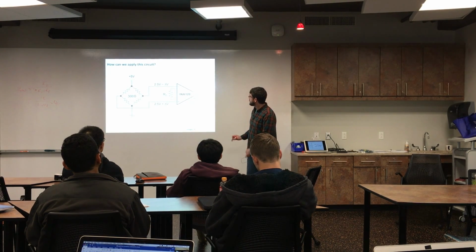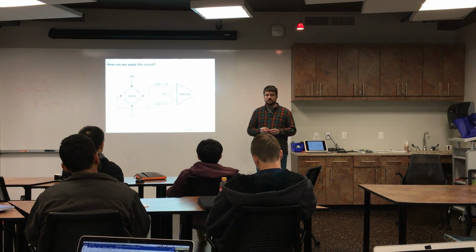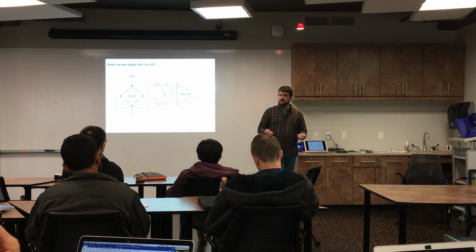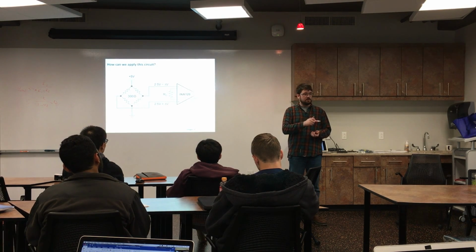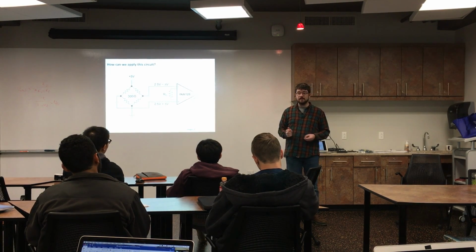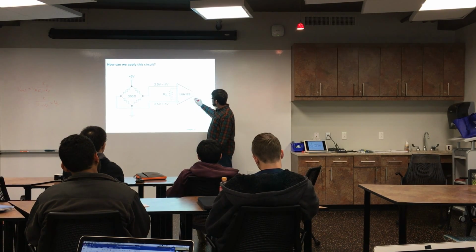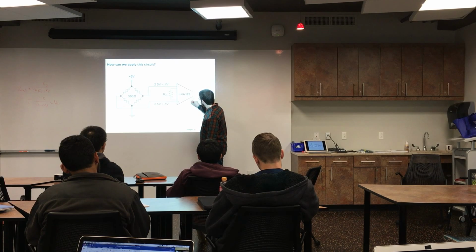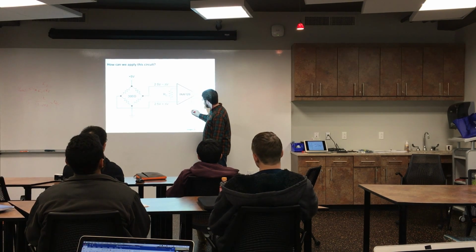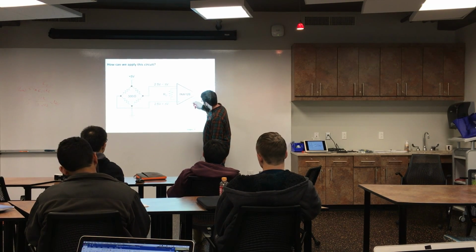But if you do need to do a little bit of offsetting, I did this with my coffee cup, because say I have 4 millivolts, but then I multiply the signal with a gain of 500 times, all of a sudden I have a pretty large voltage on the output. And I can offset that if I want 0 load to be 0 volts. And one way you could do this would be, instead of tying that to ground, you put a resistor in there. Let's say we give it plus 5 volts.